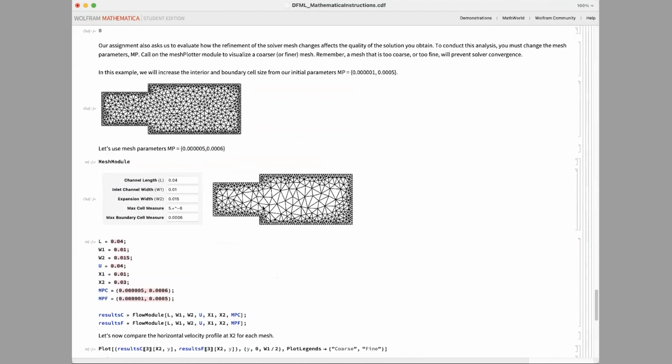So you're asking about the refinement at the boundaries? Yeah, because if you don't refine the boundaries enough, you're going to get errors from NDSolve. So we're giving them the option to see here that you can really take this refinement to the extreme, or you can leave the inside even way more coarse. We're just trying to give them the ability to visualize where their calculation points are going to be in the region. Right. And in general, this depends on say Reynolds numbers. Yep, exactly.